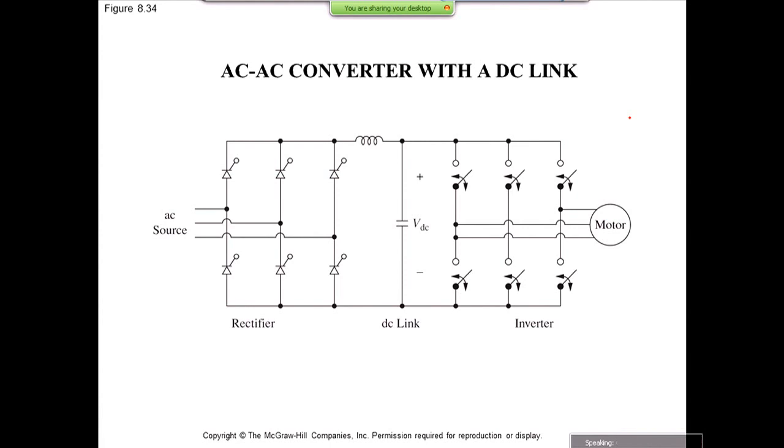Then the book talks a little bit about what we talked about last time, that a lot of times when you have an inverter, the indication is you do not really have a DC source. You have rectified an AC source to get a DC source, or a DC cap voltage kind of a thing, a link DC voltage, and then you invert it back. So this is an example of a 3-phase variable speed motor drive.